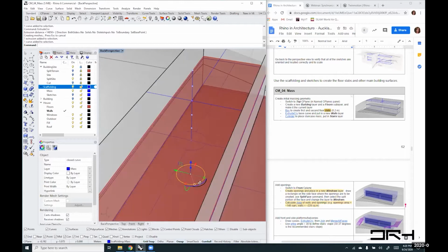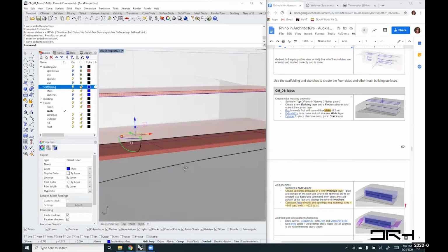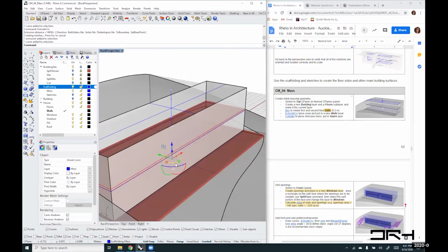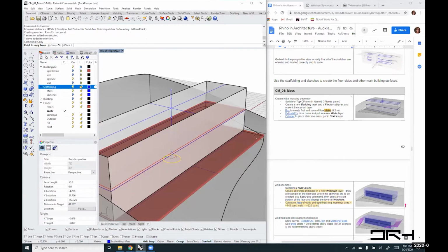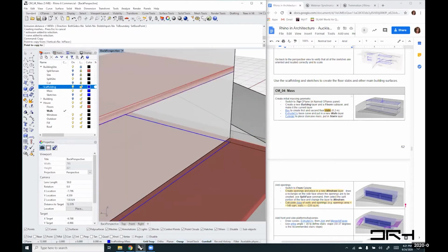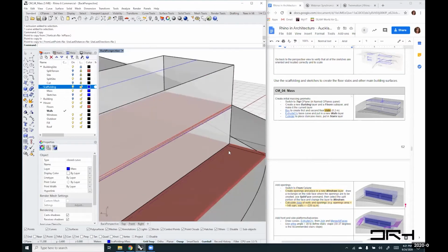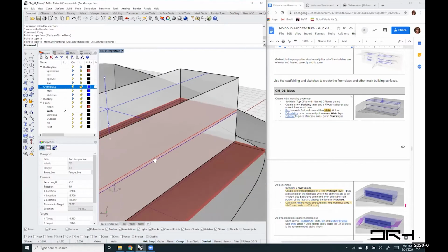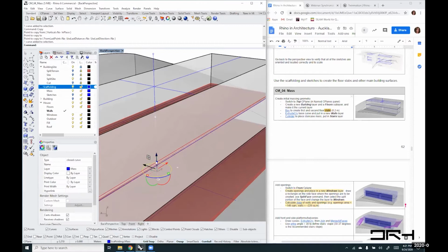as the reference for my stairs, and I'll also copy, although it's only a reference, another one on the top of the floor and use that one as my reference to also extrude here, or use the cylinder command if you want.